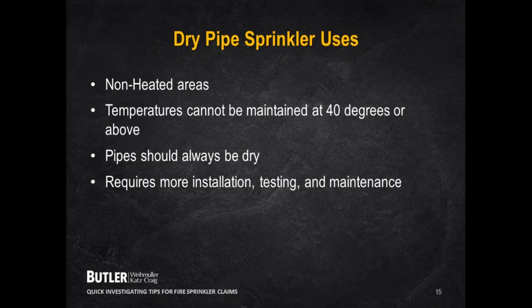Right away, when I get a fire sprinkler loss, I want to know if it's a wet pipe or a dry pipe system, because a dry pipe should always be dry. A dry pipe should never have water in it. That's the biggest subrogation alert that I could stress to you today. The dry pipes require more installation, more testing, and more maintenance.